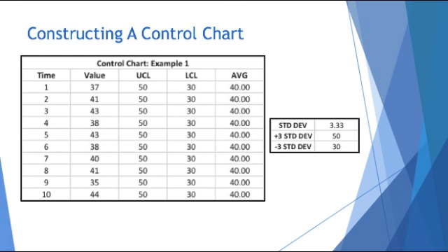curve. The rule of thumb with control charts is that you always want to be within 3 standard deviations above your average and 3 standard deviations below your average. This is also known as a 3 sigma spread, which means 99.7% of your parts will be good. That means only 3 in 1,000 parts will be bad. That's a pretty good production facility.